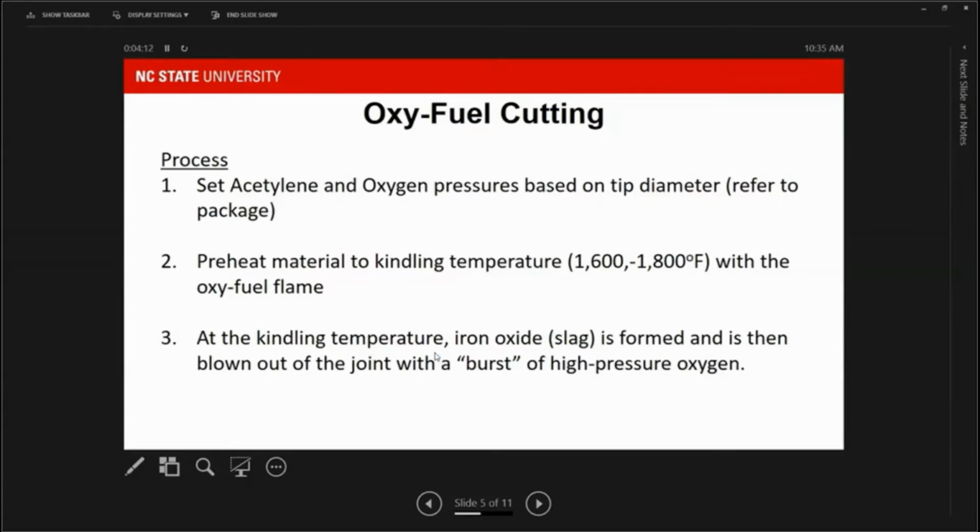We use an oxyacetylene regulator, okay? Just like the one pictured here. Can y'all see that? This is an oxyacetylene regulator. This happens to be an acetylene regulator, but we have a tank pressure gauge, we have a torch pressure gauge, and we can increase and decrease the pressure of the gas by twisting this knob. Basically what we're doing is compressing a diaphragm in here, and it's pressurizing the gas to our desired pressure. We'll get into more of how those regulators and the setups work when we talk about welding.